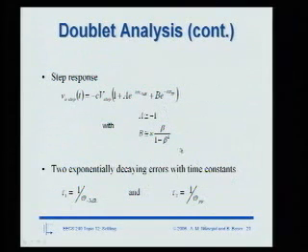But the idea is that you do get the second pole due to the pole and zero. And just like the fact that unless we had infinite precision, the pole zero didn't cancel out when we talked about them before, same story here. I have a pole, a zero, and another pole. I still feel the effects of that pole zero doublet because they don't cancel each other out perfectly. Okay.